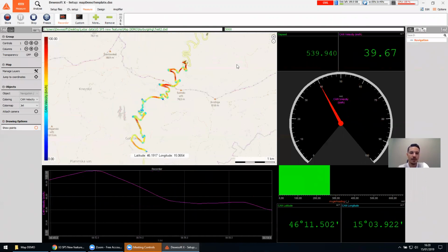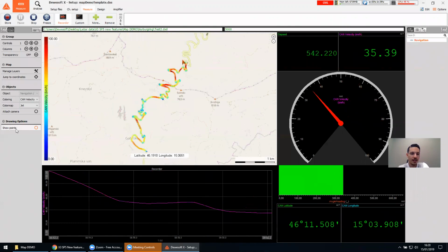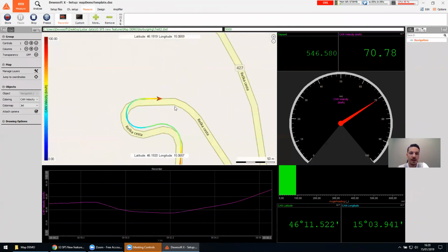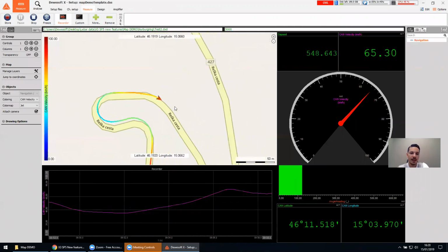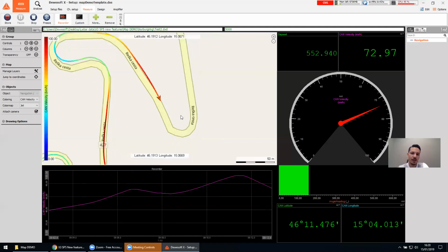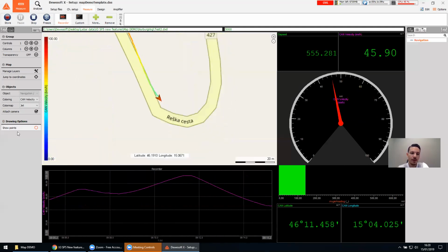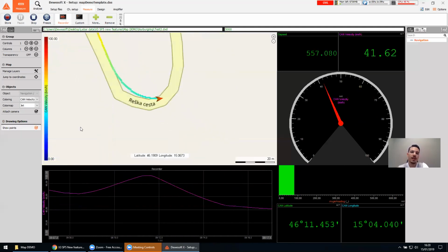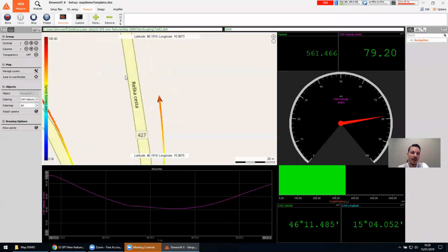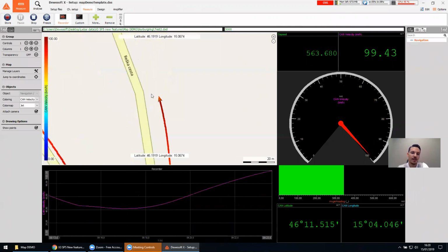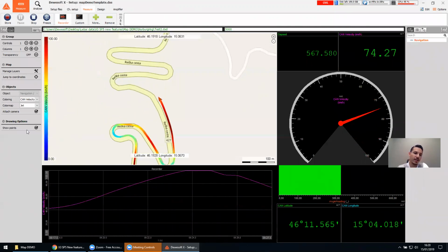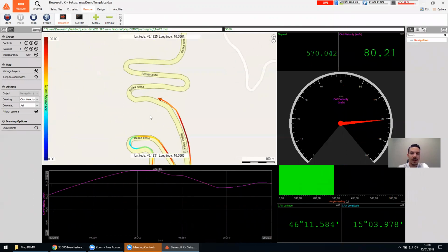And the final parameter of the map is the show points feature. So basically, if you had GPS data that had a low resolution, lower frequency, at the moment I've got 100 Hertz, you could maybe more easily distinguish between points. At the moment, this is not really apparent, but if your GPS data is not that fast, you could see individual points rather than just lines.